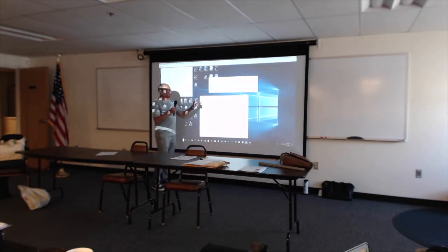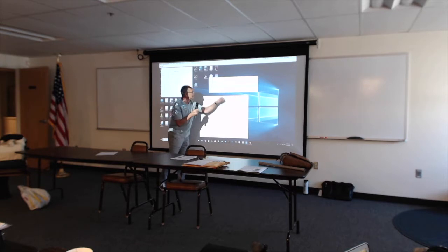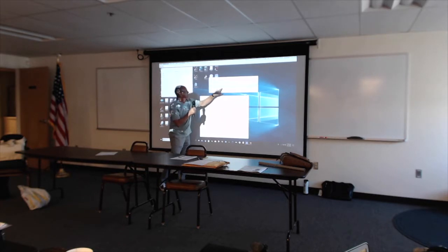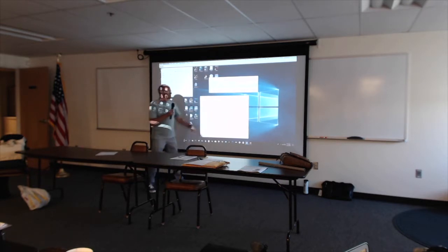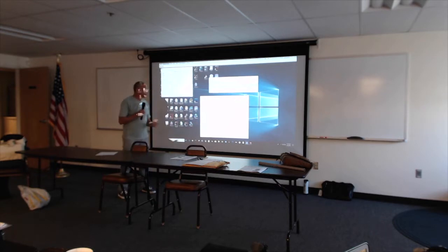One thing I noticed about this, well, let me get to that in a moment. And then the third wire is similar to that. It's 138 feet, starts here, and we go to minus 98 down here. The z-axis says we're 7 feet off the ground, so this bottom wire is 7 feet off the ground here. So these are things you have to think about when you're modeling the wires.